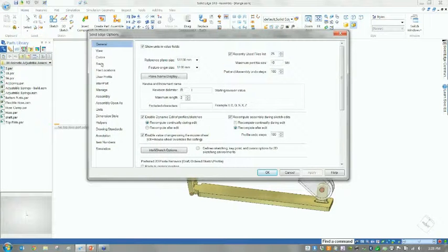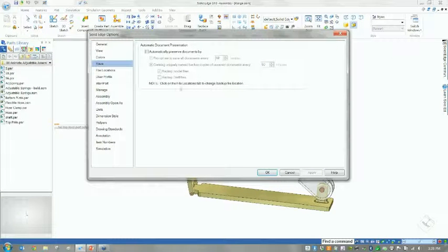my Solid Edge options. I'm going to go to Save. Now here's where your backup file is, your .baks, okay? And that's where those are. And those backup files, you notice mine are not done. If I check on that, preserve prompt, create a uniquely named backup copy every 5 minutes, okay? Needed, not needed, that's up to you. That's why the check mark is here. I don't normally do that.